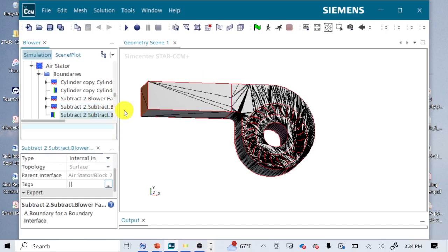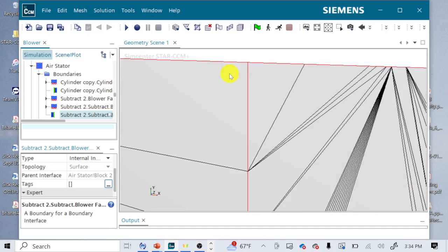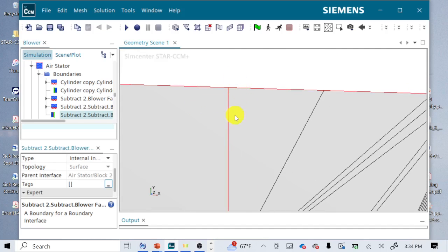Yeah. I have a question. Why would it create a problem? Isn't it just spewing out from this outlet to the next outlet? If you have a tiny cell, so if we zoom way in, it could conceivably have a tiny cell right where the old outlet was on the right-hand side and the new outlet on the left. It could have a cell that doesn't quite connect. And air would be allowed to leak out through that cell if we left it as an outlet. If we make it a wall, then no air is allowed to pass through it.